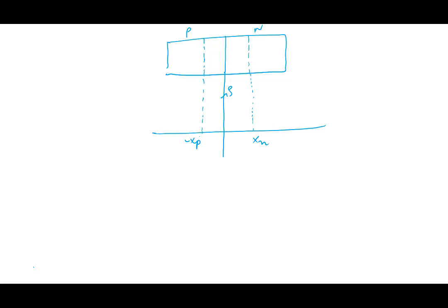Can I draw what rho would look like? Keep in mind, rho is q times (Nd minus Na plus p minus n). So if I look at this region, can you all see that it's approximately like this here?